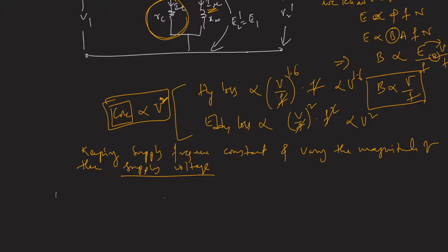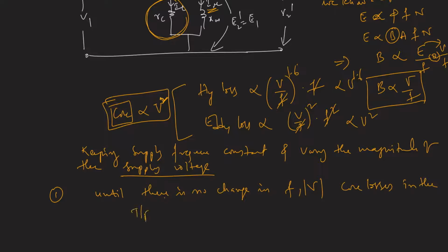So I can say that as long as there is no change in frequency and supply voltage magnitude, the core losses in the transformer remain constant, and they are independent of load.